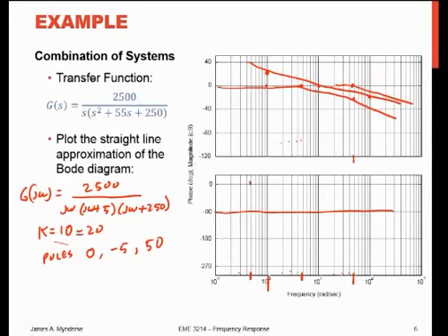From there, it's 45 at that point at the break frequency. Gets to minus 90 out here at 50. That's for the first one. And then it's horizontal here, horizontal there. And then I have the one centered around 50, which starts here, hits 45 at 50, and then hits minus 90 at 500. So that's a straight line there. And it was 0 dB up here.